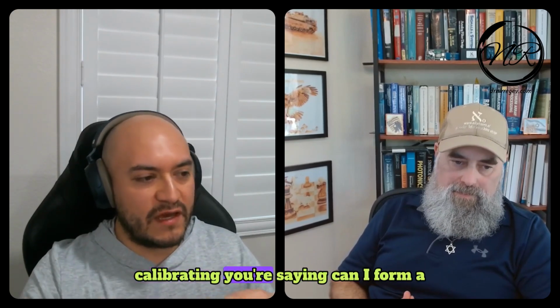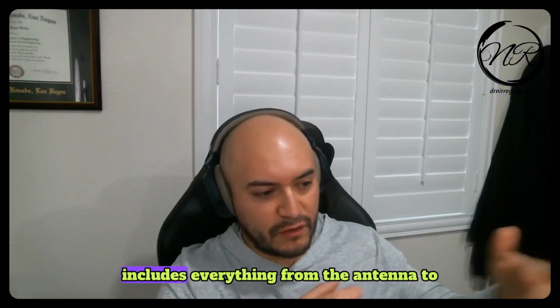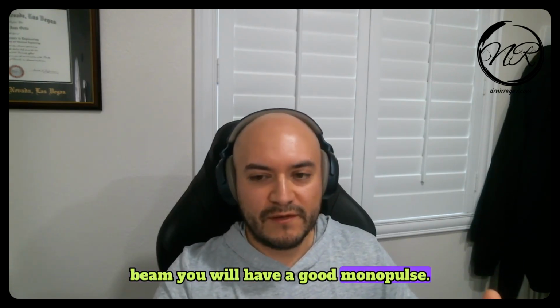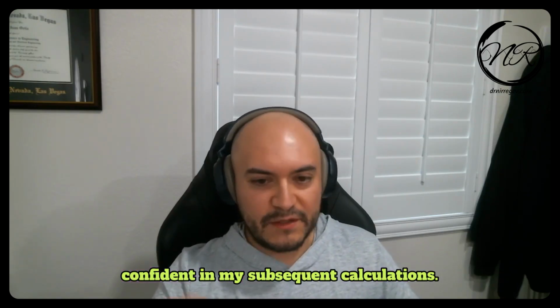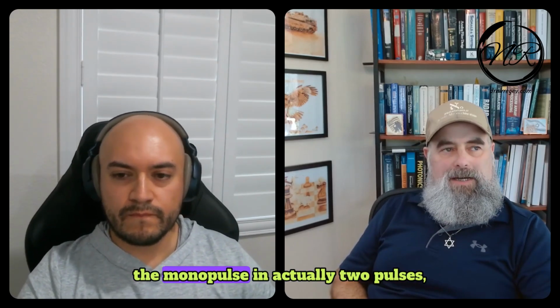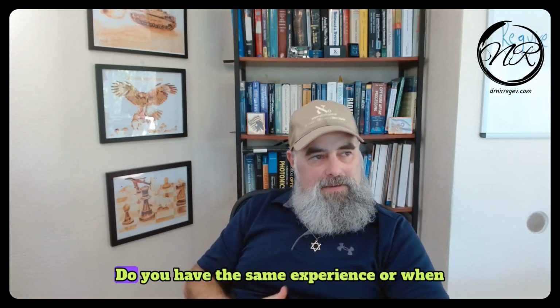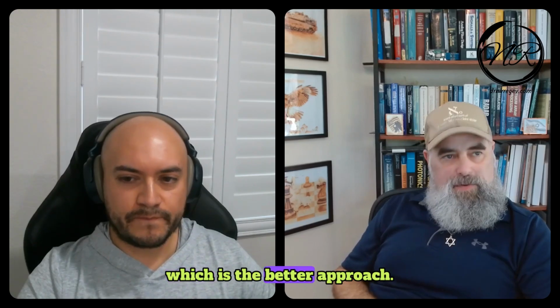Because when you're calibrating, you're really asking, can I form a good beam? If you can form a good beam, which includes everything from the antenna to the electronics, you will have a good monopulse. As long as you can prove to yourself that you're forming good beams, you're confident in your subsequent calculations. Sometimes I encountered monopulse in actually two pulses, one looking right, one looking left. Did you have the same experience, or was it always the same pulse, which is the better approach?